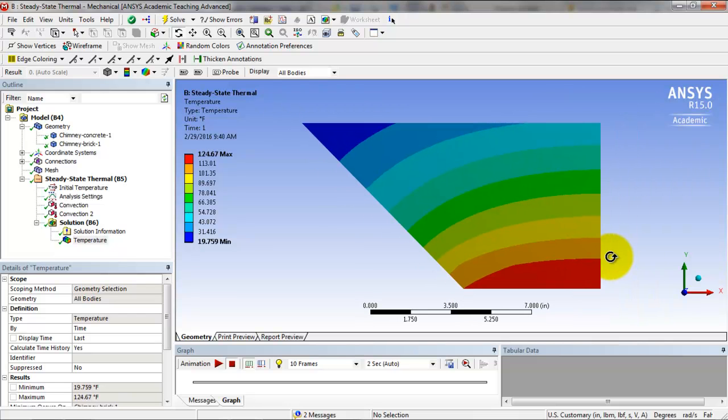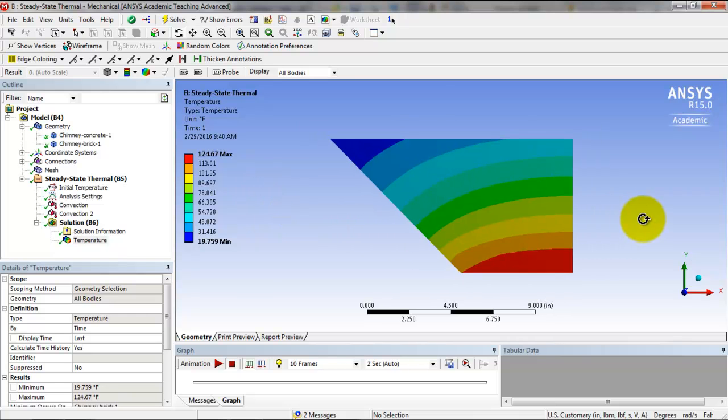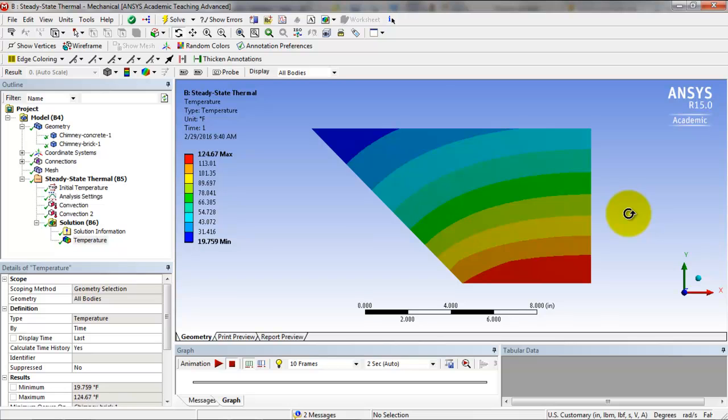All right, so there we go. So we got that roundedness that was happening, and so it rounds into this other symmetry half that would have been over here, as well as the symmetry half that was over here. And we're able to do it all, and you see the temperatures coming out very much the same as what we saw in doing the full model. All right, but much smaller, and we could probably use the same number of grids that were there originally on the original model. It would run much faster because there'd be fewer nodes overall because of the symmetry that we cut it down to. But hopefully you get the sense of what that symmetry can provide us and how to get there, cutting things down in SolidWorks.